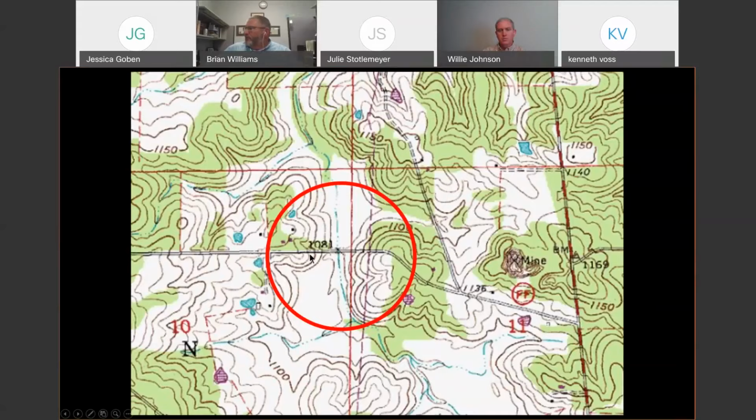More on this direction over here. Okay, so it's like a small ditch probably right along in here. So you just have to study the erosion control plan. Again, if you're out there and you see where the job, get out on the job site and you're looking at what's on the ground, you can verify that through some topo maps as you're in the office.